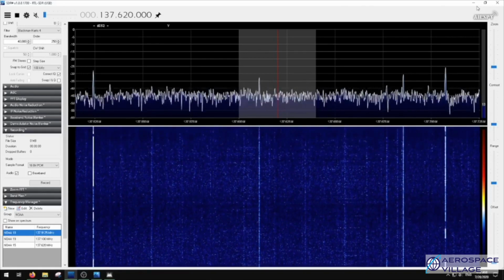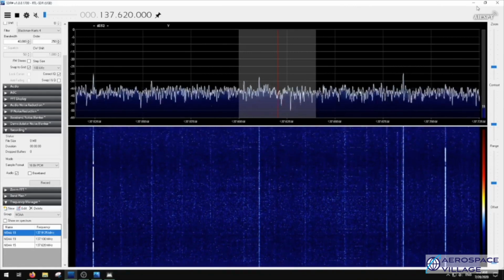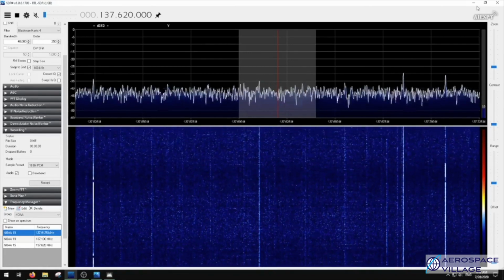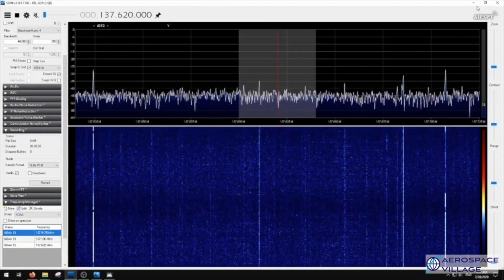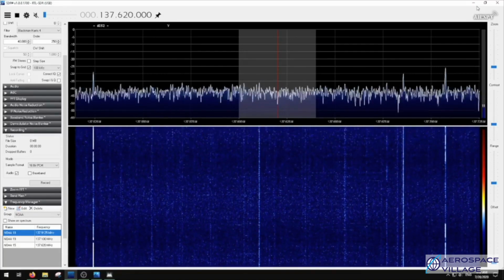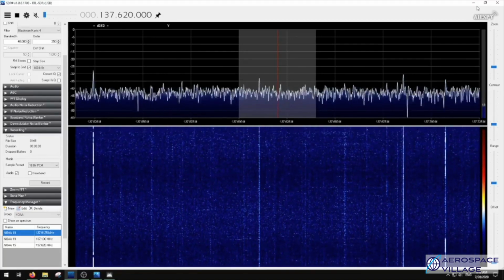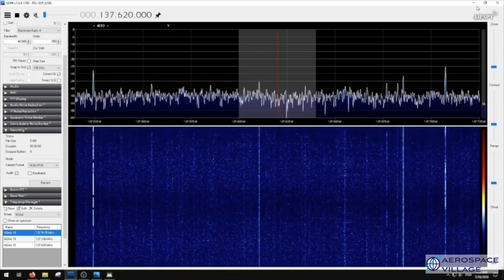In terms of an antenna, the signal is right-hand circular polarized, so helical antennas are wonderful. However, there is quite a bit of success to be had in just a very simple horizontal half-wavelength dipole. A V dipole oriented north-south works really well, and it's what we used.